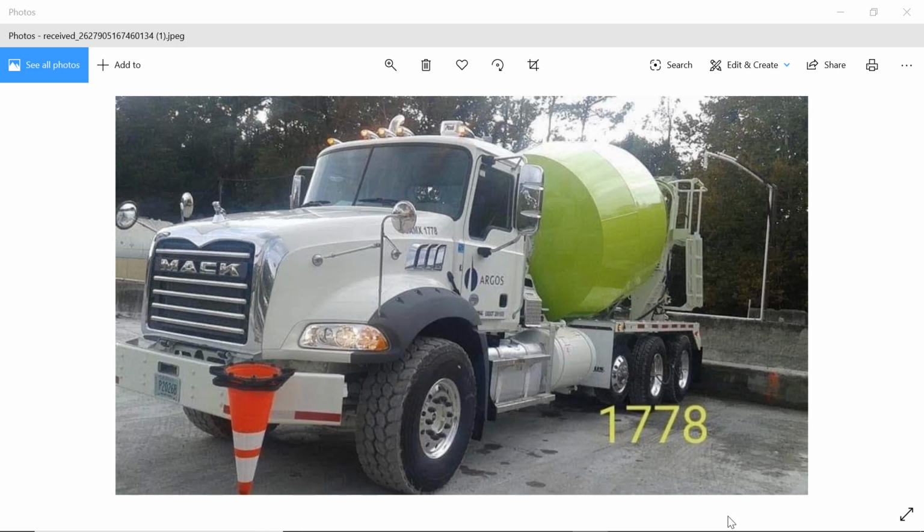Adjustment due to extra water in the coarse aggregate is equal to 1,620 times 1.035, which is equal to 1,676.7000, which is equal to 1,676.7000 minus 1,620, which is equal to 56.7000 pounds free moisture.